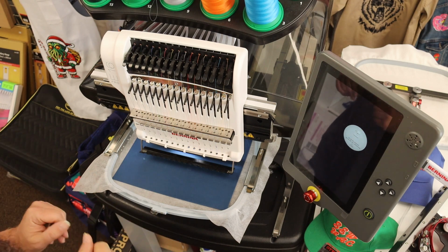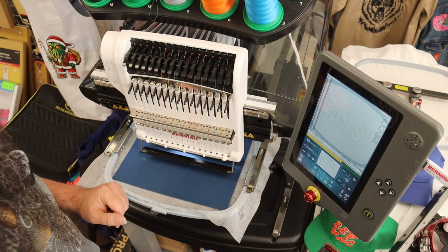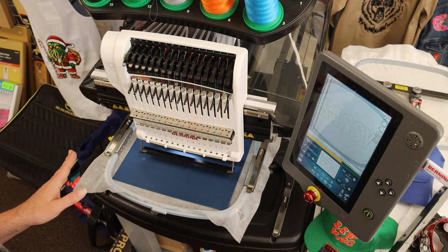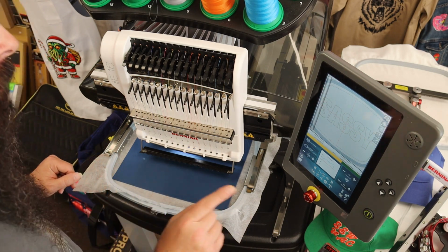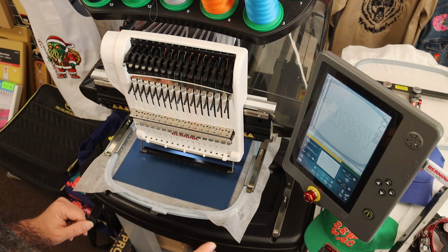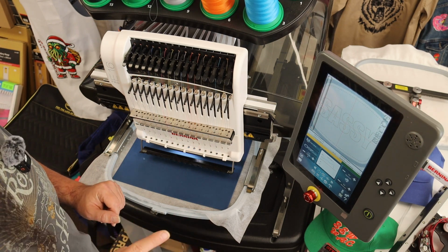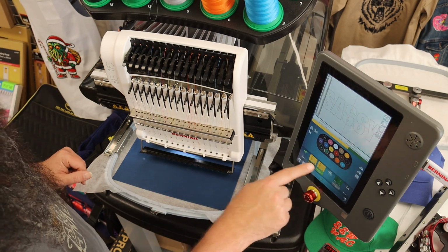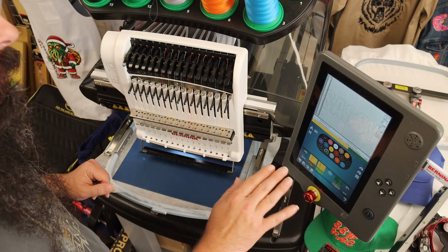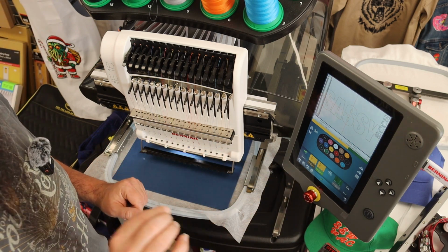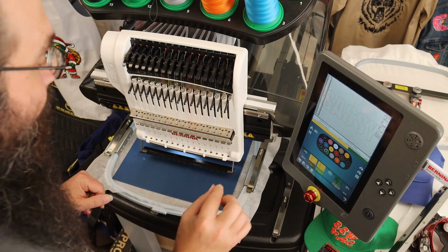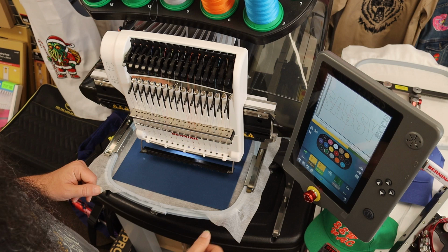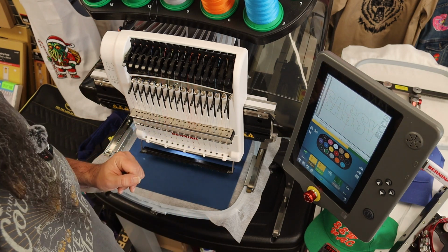So anyway, that's what I'm going to do, and I'm just going to have this start my design, and I don't need to be involved in the first part of the design. But if you are using a multi-needle, you do need to make sure that you set the machine to stop, and I can do that on my machine, to stop before the last color. You only want it to sew out the first 2 color changes in your design. That way we can go and do the stuff that we need to do before we sew out the last color, which is going to actually sew the shirt to the foam.